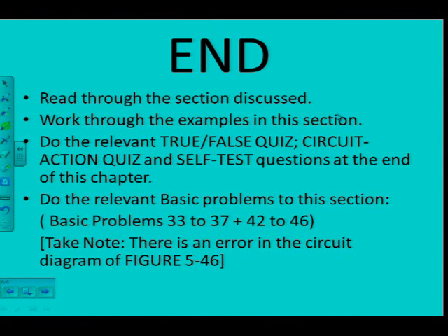Also, make sure that you see how this guy in this problem used the multimeter. Remember, I've told you we read from left to right. So if I ask you to measure VC, you put the red lead on the collector and the black lead on ground, and you will get a reading of the voltage at the collector. But I can see in this case that he swapped it around. The only purpose for that is he wanted to display positive values, because they should be negative.